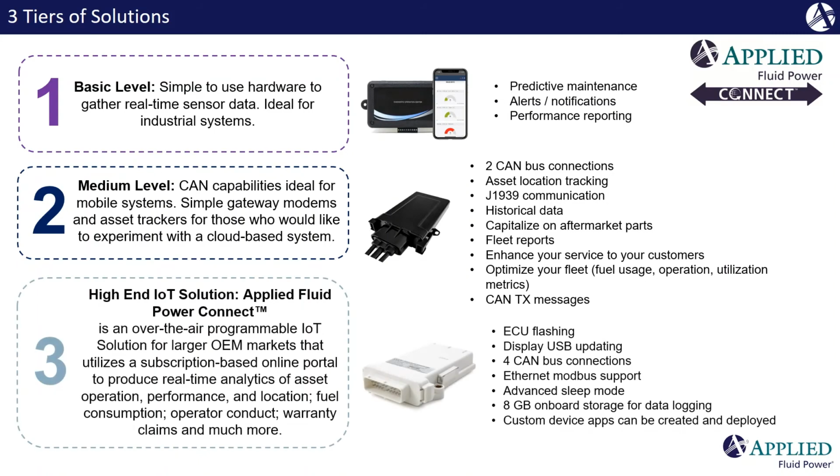The top end is going to be level 3, which is the high-end solution. This is the Applied Fluid Power Connect top end. This is going to up it to 4 CAN bus connections. It's going to give some level of Ethernet Modbus support. It's also going to support any of the ECU flashing that we talked about a little bit earlier in the presentation. It's also going to give you the ability to update displays via USB and any other devices that can be updated via USB.